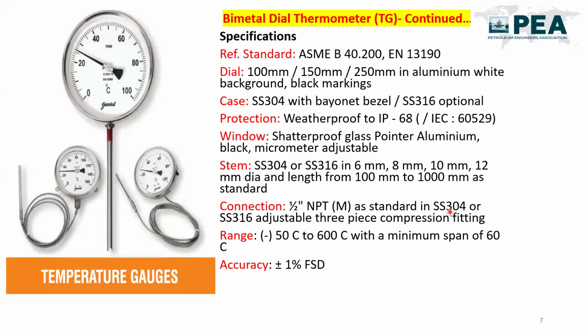There are various connection sizes available with the manufacturer, so whatever connection size philosophy you are following in your project applies. Now the question is, where will you get the connection size, and how will you know what connection size to choose for a particular thermowell? Guys, the connection size is generally mentioned on the P&ID also. It is also available in your instrumentation design basis, which lists the different process connection sizes to adopt for different instruments, like temperature, pressure and flow instruments. Range we have already discussed.